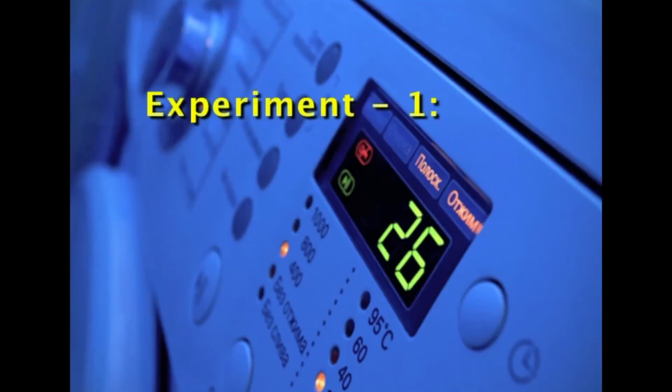The test protocol. There are different tests to be conducted for testing the input test, insulation test, leakage current test and performance test, which can be used to test the efficiency of a washing machine. Now let us look into the input test. The aim is to check the wattage of the equipment.